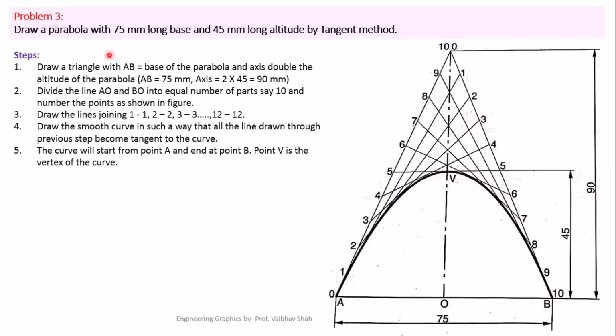Draw a parabola with 75 mm long base and 45 mm long altitude by the tangent method. So in this case, the dimensions of the parabola itself are given.